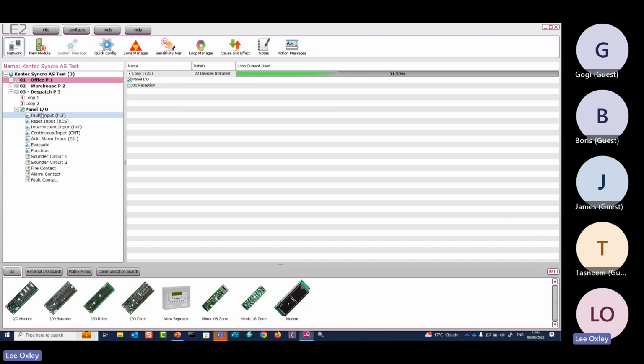So, for example, I did say you got those 5 programmable inputs where you simply get 0 volts. I used to take a 0 volts, hook a piece of cable inside the panel, a 0 volts out to a normally open key switch, I mount on the side of the panel, normally open, I bring it back, and I went into the fault input, because you very rarely use a fault input.